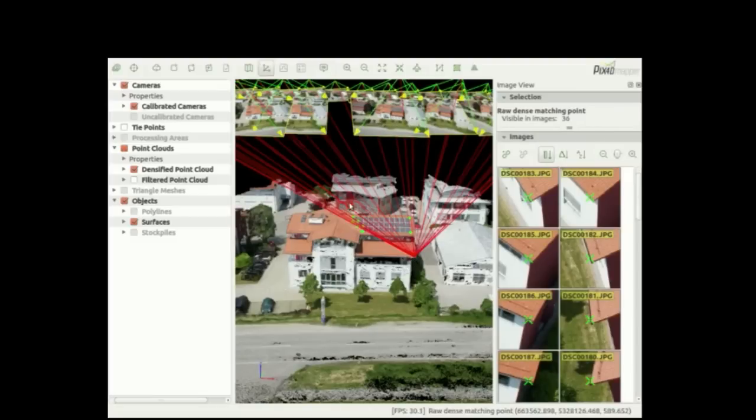The intersection of these rays with the images is shown on the right, and you can see here that this point has been extracted from these green positions in the images. So with this editor we now have a nice ability to annotate 3D points in a CAD-like manner in 3D, and at the same time to measure these same 3D points in 2D in a more photogrammetric approach. So this is a nice connection between 3D and 2D, which combines CAD and photogrammetry approaches. This is the first important point.